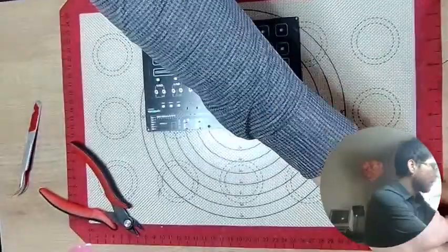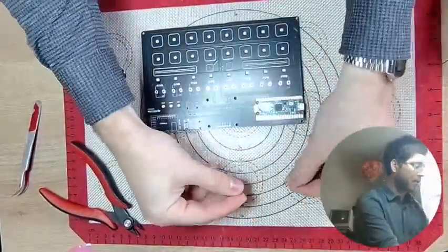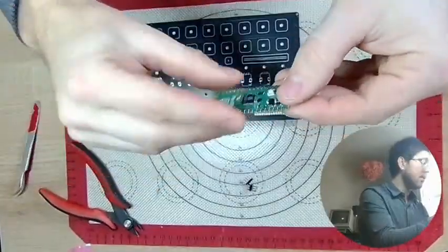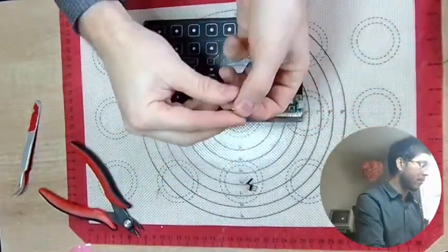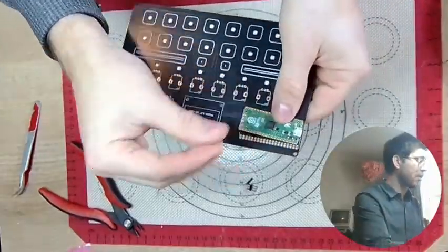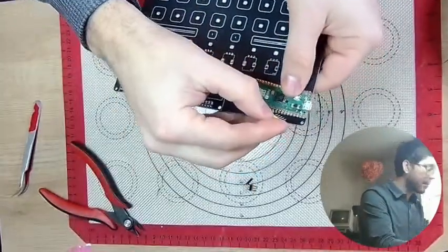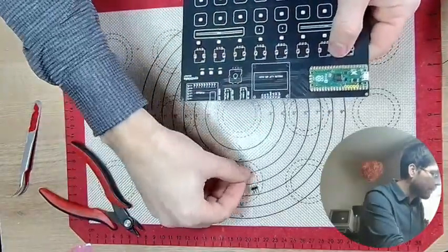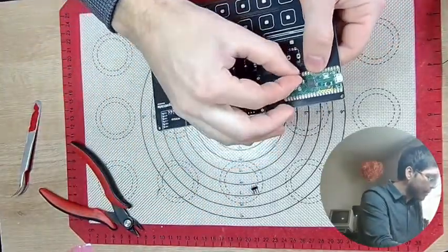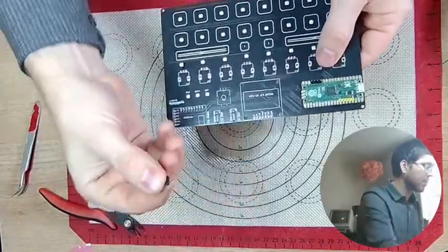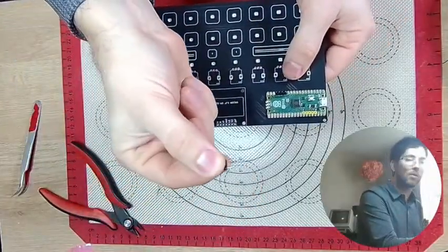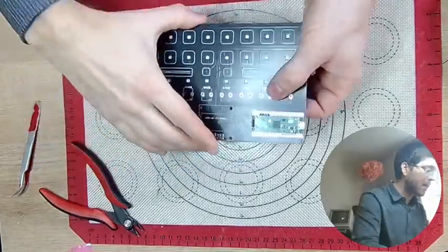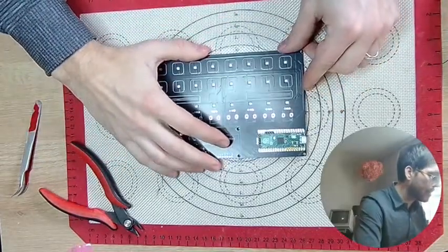Okay, cool. So, super big trick for the Pico, because we're gonna use the castellated pads on it to get a really slim profile on the board. I'm gonna use these little pin headers to help us align. So I'm gonna put some in over here, and I'm gonna put some over here. Make sure that everything is really lined up, and if you're really good at it, you'll use a little 3-pin header over here to line up that debug port too while we're at it.